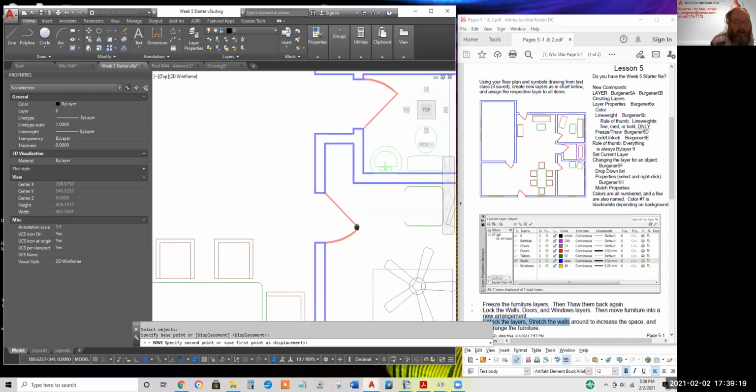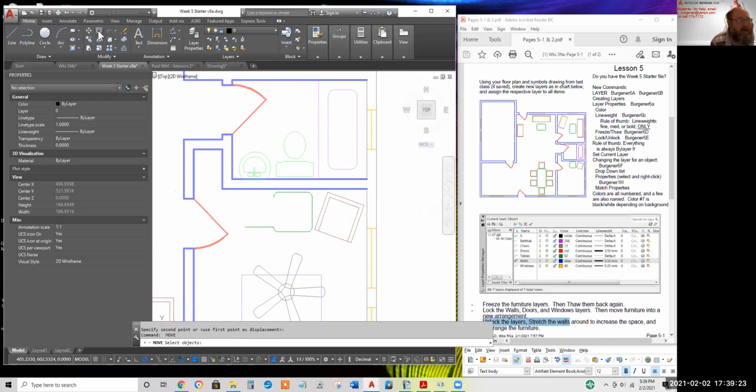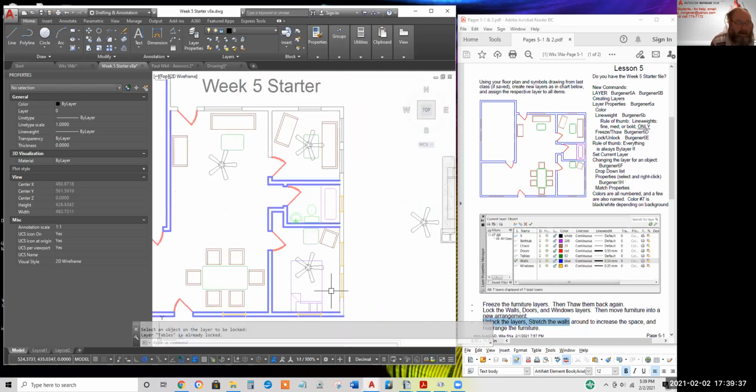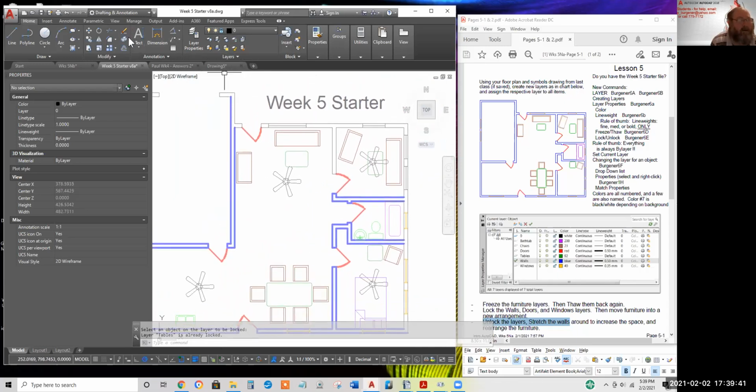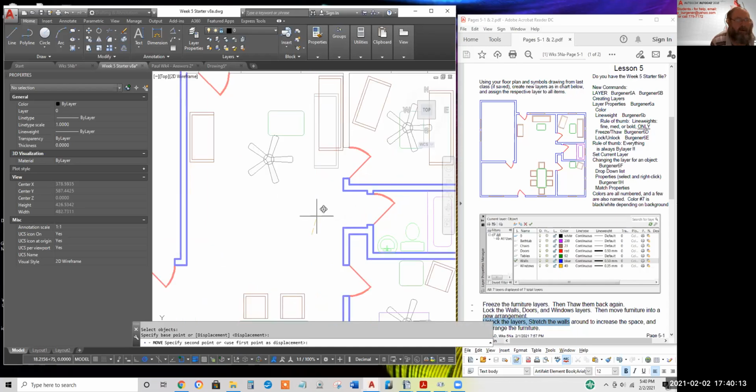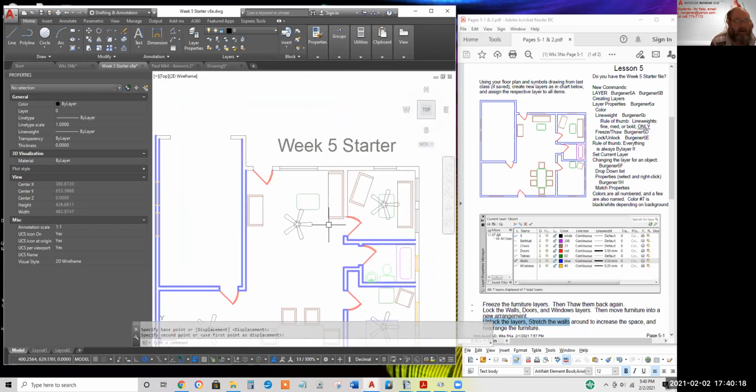Put him back where it goes. Rotate it. Lock the tables layer. Might be a case where I'd answer yes, I want to erase the source rather than putting 2 sofas in the room. Sure, P for previous would. I don't believe L for last would select the new mirror copy. Maybe the last piece of it.